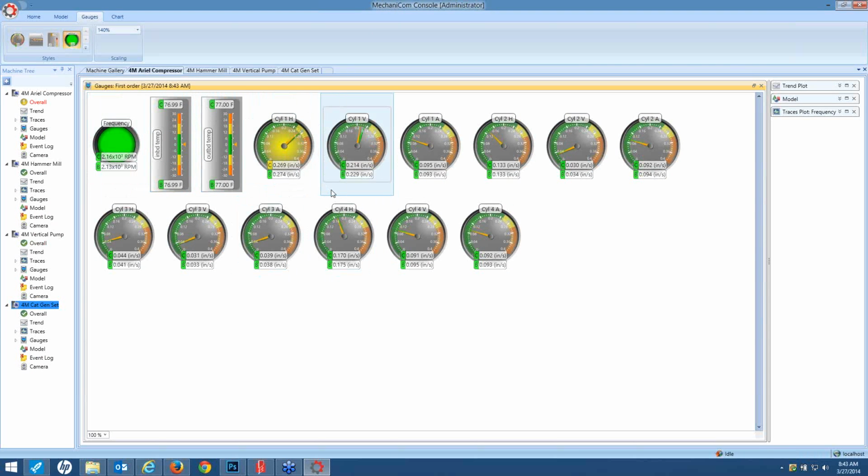So if you're looking at more bearing related stuff, it may be the third order. You can tighten it down instead of leaving it where you would be for running speed, where you would want a higher threshold. Obviously, you're going to see the highest peak there in most cases. If you want to be more sensitive to a magnitude change at the higher orders, you can have tighter alarming limits there. So you have higher sensitivity, and it'll let you know that something's going on, even though at running speed maybe your magnitude didn't change.